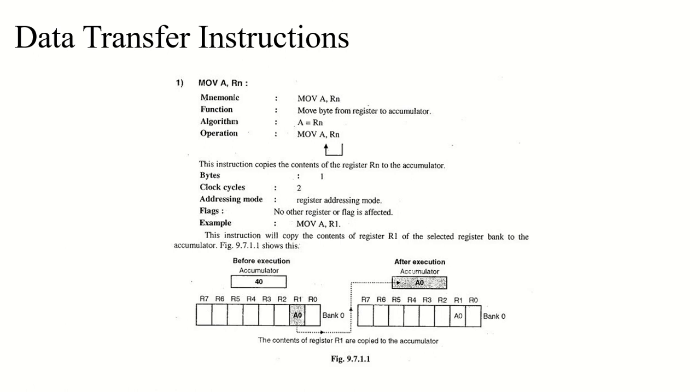Even though you may have seen this in the previous instruction set of 8085, let me repeat it one more time. The instruction copies the content of the source location to the destination location. The content of the source location remains unchanged, and it's the most flexible operation, allowing 15 combinations of source and destination addressing modes. Depending on the type of transfer, the number of bytes required can be 1, 2, or 3, and the number of cycles required can be either one cycle or two cycles at most.